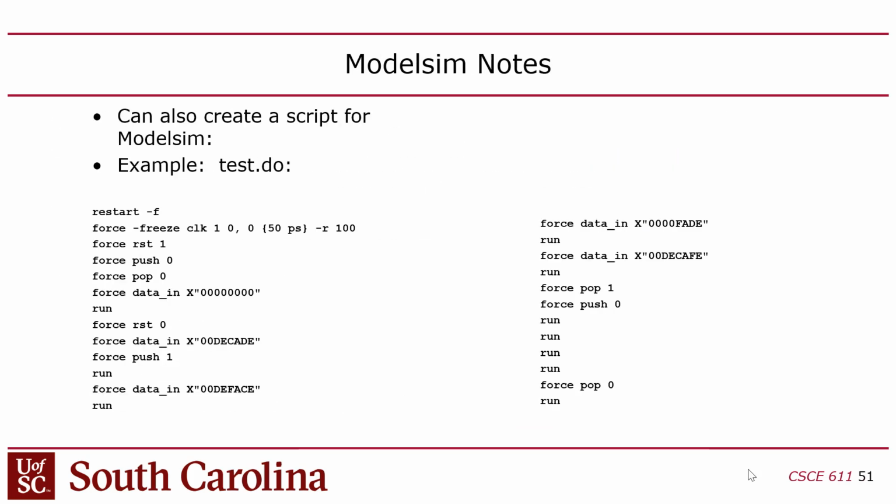I have another question about the FPGA and the testbench. The switches drive the LED segment. If you're doing an automated test bench, can you overdrive that by forcing a signal? Yeah, that's exactly what you want to do. So there's no error created by having two sources? No, because in the top there's nothing driving the switches, since they're going to be driven by the physical switches. And in SimTop, right now there's nothing that drives them either, but you could put that in.